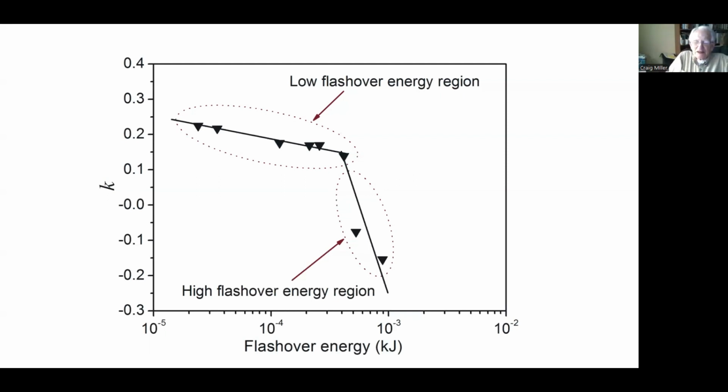You start out with an initial set of device, insulator, whatever geometry. You get an initial flashover, subsequent flashovers are higher. Eventually you reach a limit, but this is of course of great importance, particularly practical, because often devices are built, assembled and tested before they go into service. And the testing can improve the hold-off voltage significantly, and very often for applications where your device is kept sealed, the improvement in hold-off voltage persists.